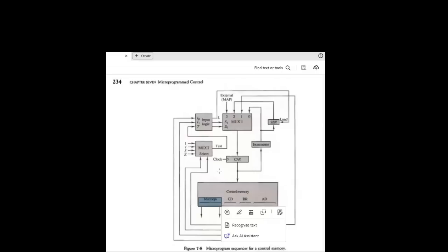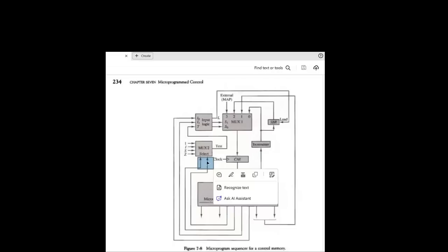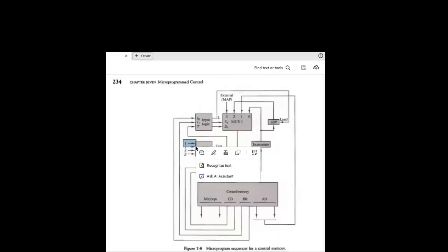So in this figure, what they have shown us is, from the micro instruction that is selected, the CDR also provides the next address information to your next address generator. So this is the information that is provided. You are providing the value of CD from the selected micro instruction. Whatever is the value of CD goes inside this multiplexer. If 00 is selected, this is 1. By default, 1 would be entered over here and the test value would be 1.